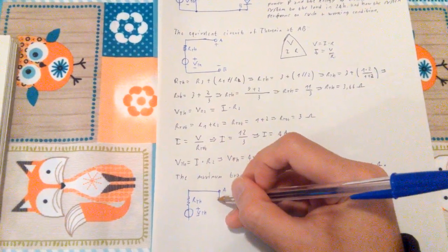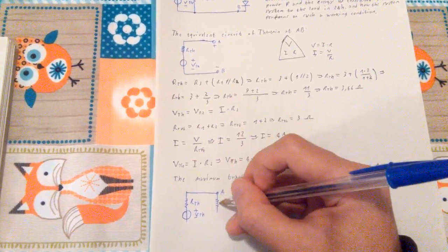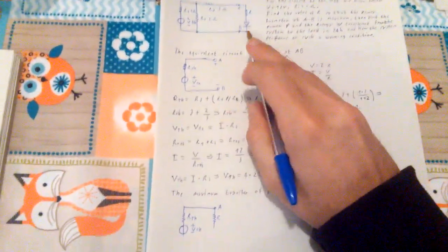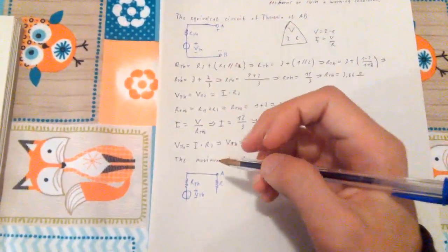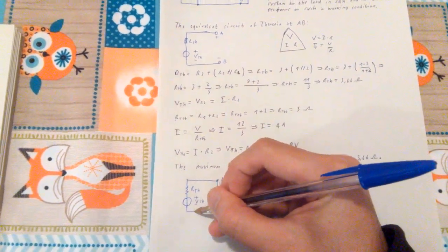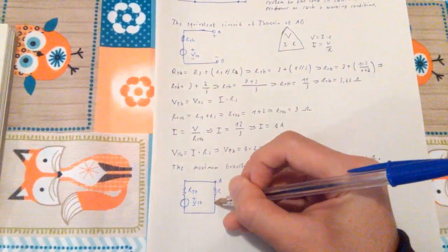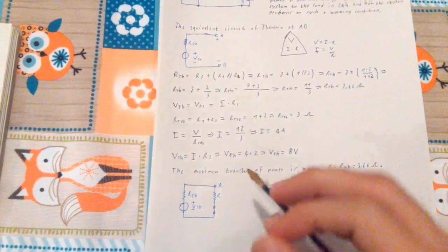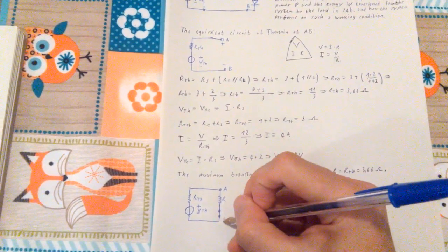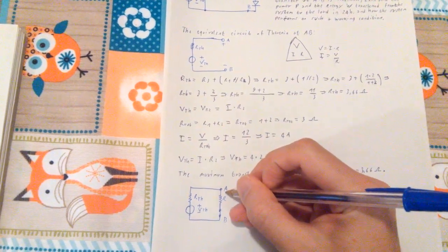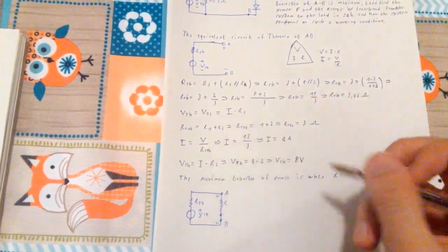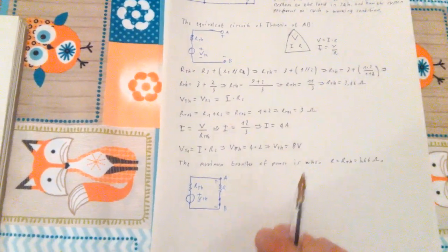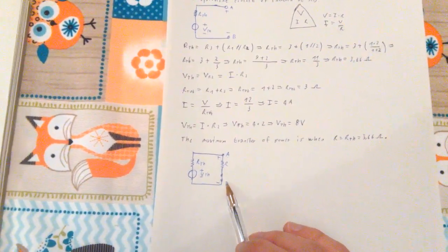But down here we would have R. And this diode, I just replace and swap with a short circuit because it's going to let all the current flow through. So this is A, this is B, plus, minus. Now, this is the Thevenin equivalent circuit.